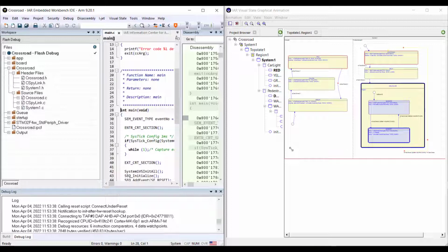And there are of course way more features that you can make use of from the model side. As I mentioned, importing different models, or when you set breakpoints or look into registers in this scenario, you can even set breakpoints on the state machine level. So it makes it very handy and powerful to solve your problem in embedded systems. Or if you think that you can reuse the same code that has been generated here for the embedded system, you could maybe generate C# or Java and solve the problem of your app that maybe is going to be used in your smartphone.